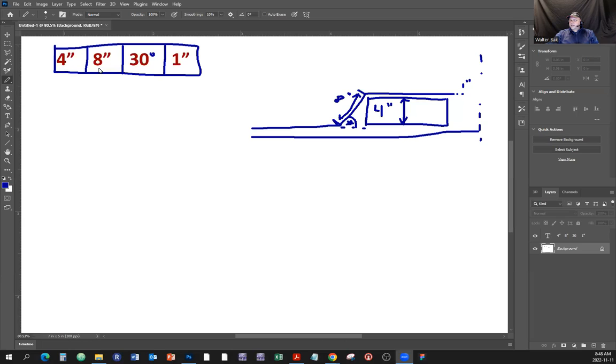The table on the sticker says we have to make the bending points 8 inches apart, and the whole pipe is going to shrink 1 inch, which means if it was a straight pipe, after doing the bend, because it's going to retract when you bend it, this distance right here, from here to here, is going to be 1 inch less altogether. How do we calculate that? Let's see the formulas.